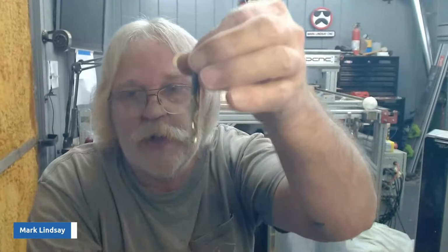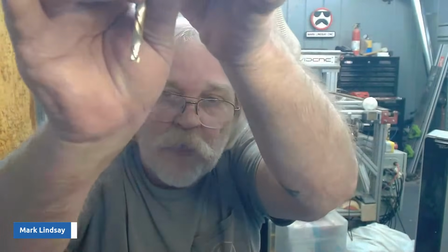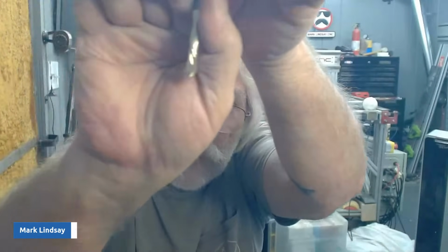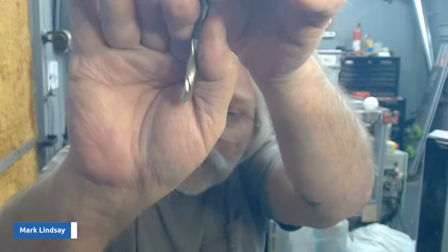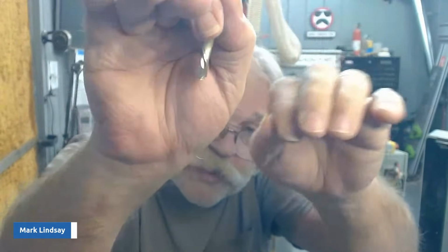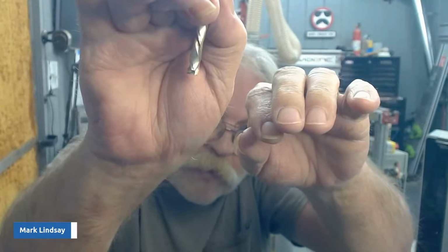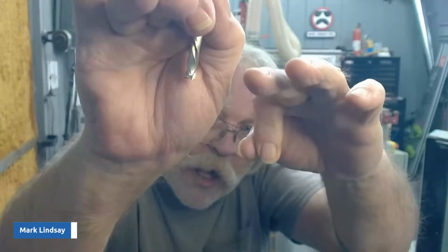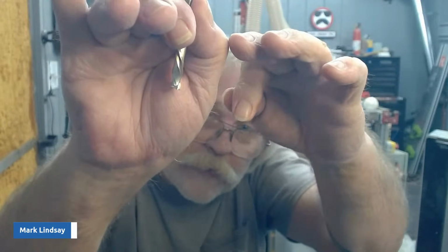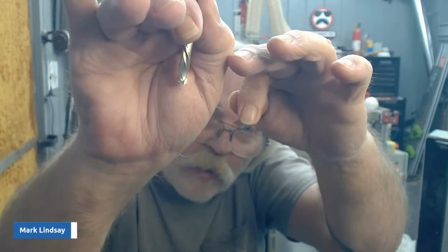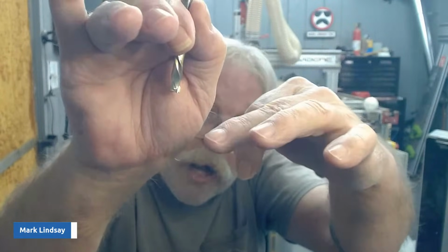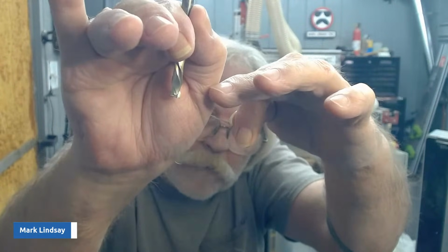Anyhow, the reason that I would use a thin first pass is with a compression bit. Now, this is a Jenny bit from Cadence Manufacturing and Design. Hashtag not sponsored. And it was designed with home hobby CNC routers in mind. What a compression bit is, the top portion of this bit is down cut, but the bottom portion is up cut.